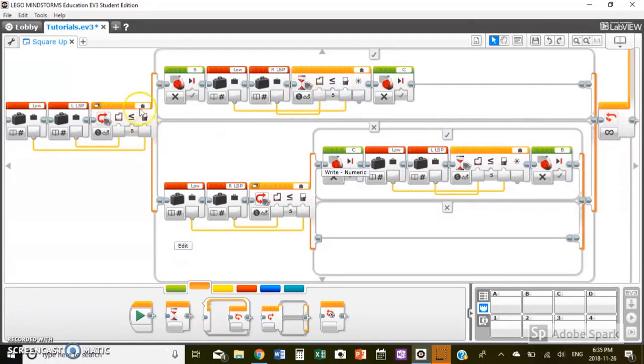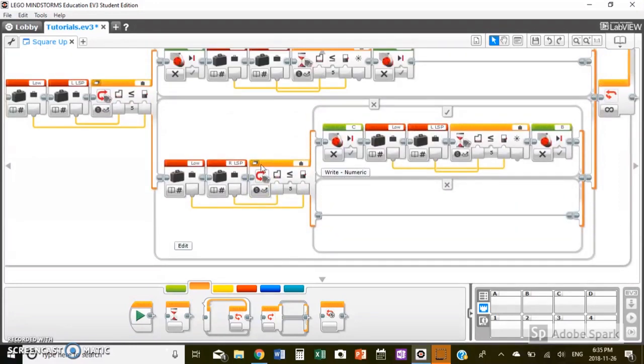So now, if it hasn't sensed anything with the left light sensor, it's simply checking if the right light sensor has detected the black line, and if it has, it stops the right motor, and it's waiting until it sees low again with the left light sensor to check the other one, and then stops that respective motor.